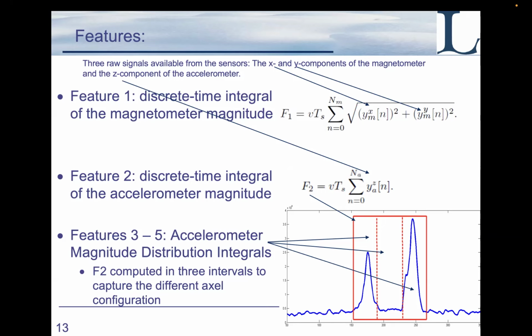You mark it as the beginning of the window. Then when it returns back to the floor level, the noise level, you end the current period. You monitor again, the signal starts to increase, and in this way you define the areas of interest of a signal.